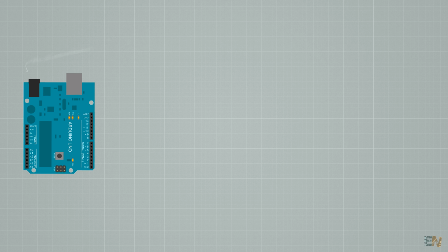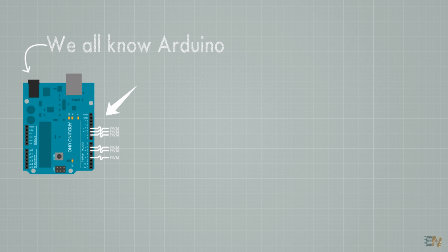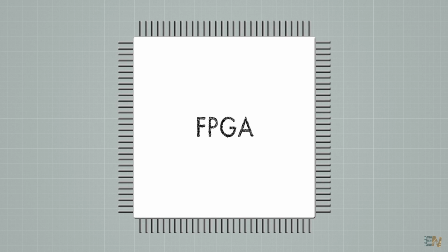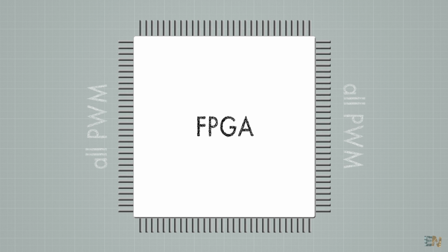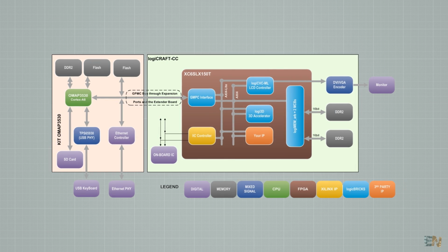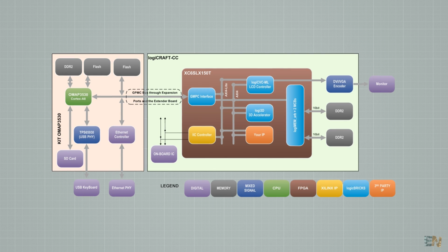A good example I like to give is the use of PWM signals. Usually microcontrollers have a limited number of PWM outputs because inside of the microcontroller there is hardware for only that amount of PWM signals. But using an FPGA I can make each of the I/O pins a PWM signal if I want that, and usually an FPGA has a lot of pins. Also, if you were to work with graphics or more complicated processing, FPGAs are a better solution. Not easier, but better. So let's start with Verilog.